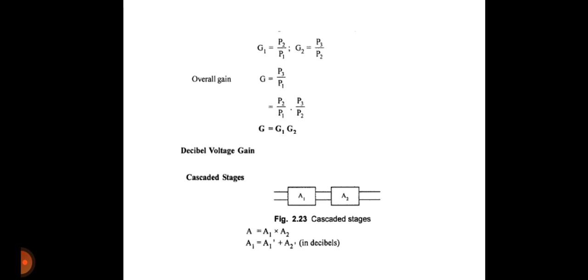In multistage amplifiers, we have to do the analysis of two-stage amplifiers. Already in the previous topic I told you how to analyze any transistor amplifier circuit by following certain steps. First draw the actual circuit diagram, then short the coupling capacitors and emitter bypass capacitor, next short the VCC, that is make it ground, next locate base, emitter and collector on the circuit diagram and start from these points. Next replace the transistor by its h-parameter model. The same steps should be followed even for multistage amplifiers.